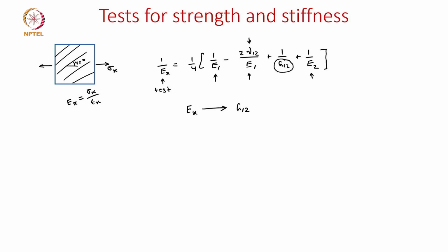But at the grippers, whether we allow this shear to occur or not will play a role on the measured loads. So as we see, if you look closely, there are some problems even with this test. So people have come up with better tests, but bear in mind that testing a composite under shear is a challenge. There are tests which are now better, but each test has its own limitations.